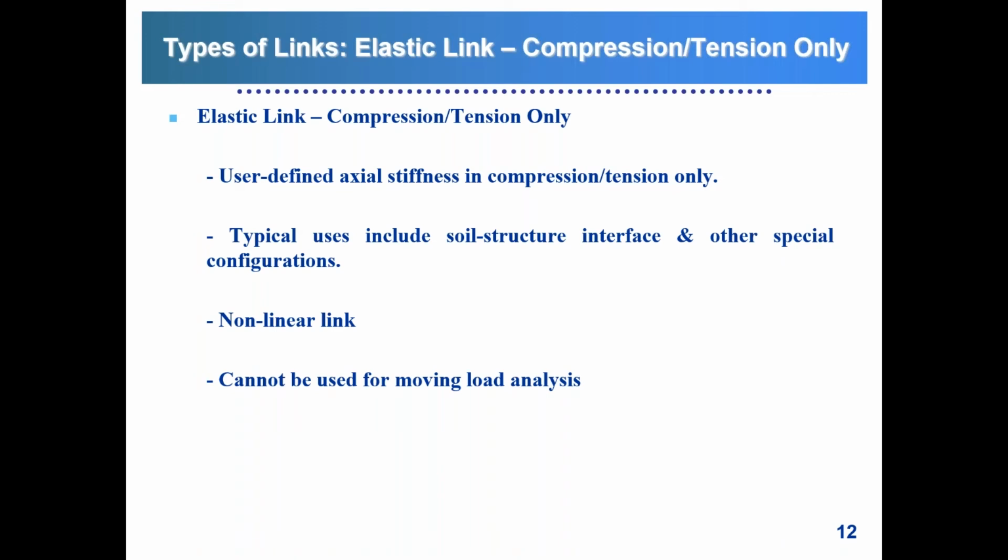So if you need to do a moving load or a live load analysis for a structure where you have these links, essentially you're going to have to come up with different locations of the truck that you want to investigate and have that as a static load, and then run the analysis based on that static load or series of static load cases to be able to capture the governing effects.